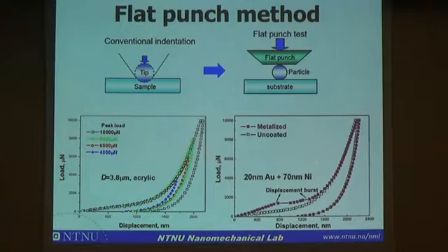And there are metal coatings, two layers of metal coating: a nickel inner layer to provide adhesion to the polymer core and conductivity, and a gold outer layer to protect the nickel layer and further strengthen the electrical conductivity. So we could see that we are able to capture the difference between the coated and the uncoated particles.